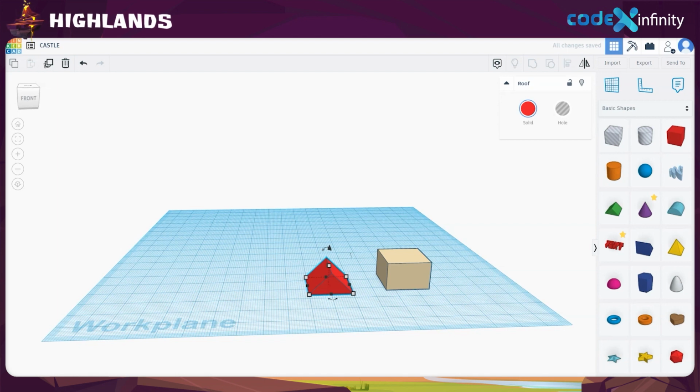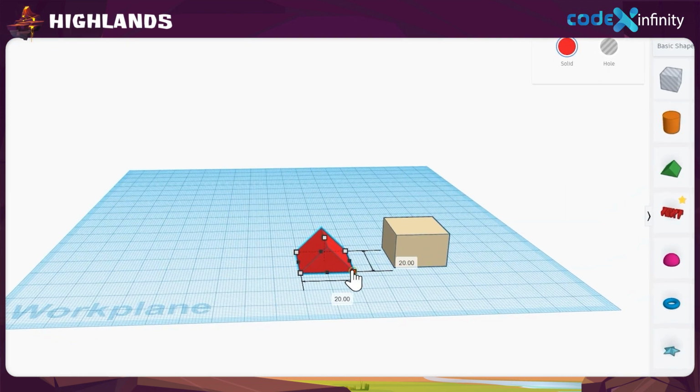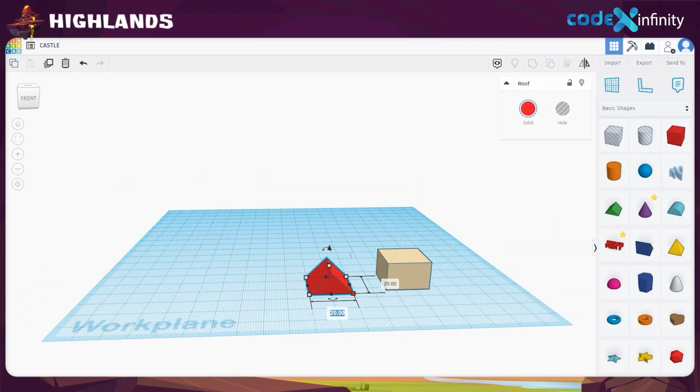Now what? Of course, the dimensions. We can now set the dimensions of the roof by keeping the dimensions we give just to the wall structure in mind. Then click on the white handle at the right bottom of the roof shape. Now select the length to set it as 26 and press Enter key. Also click on the value of width to assign it as 24 and press the Enter key. Alright, the length and breadth is set now.